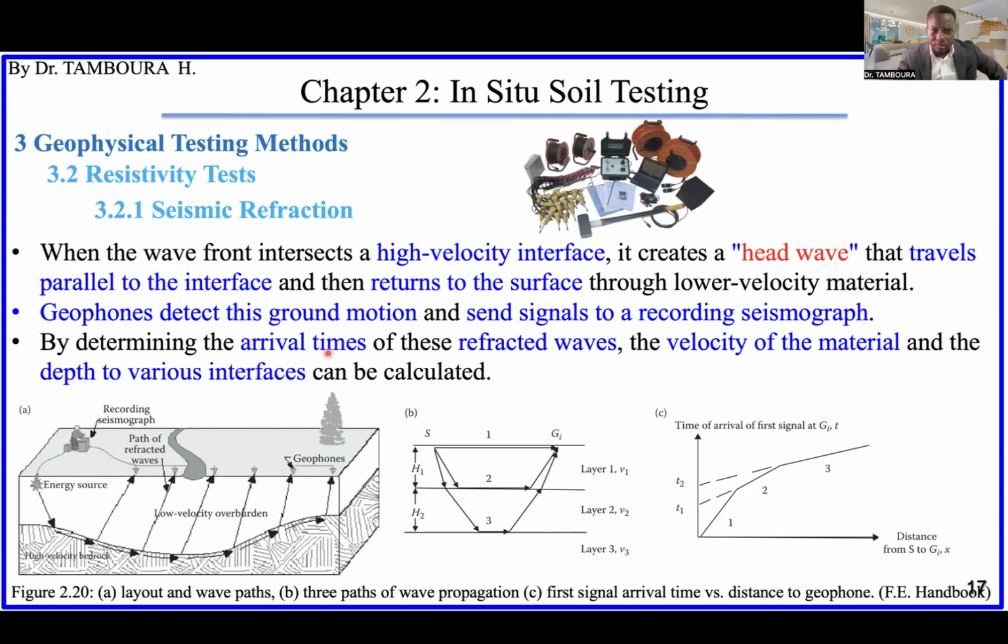By determining the arrival time of these refracted waves, the velocity of the material and the depth to various interfaces can be calculated, and I will show you soon enough how to calculate the depths. Okay, the depth of this soil layer, and also the velocity and everything.